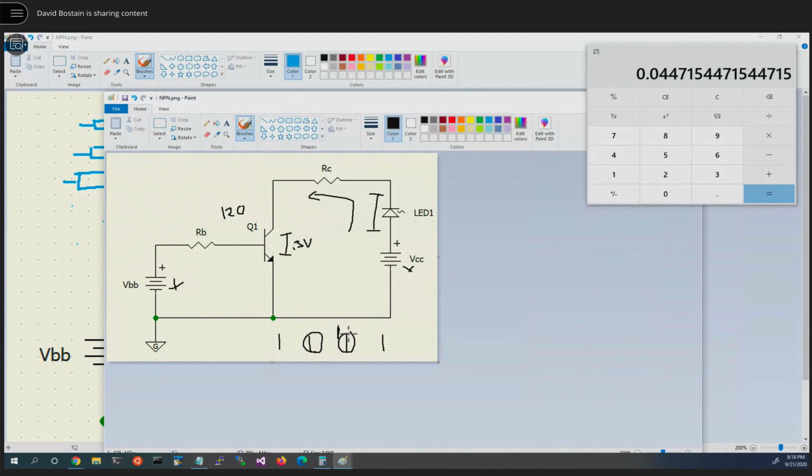Because once you work the problem and put in all the tolerances, this might exceed a range where it's not bright enough to be seen. Whereas if you came down here, it may get close to its maximum value, but it might still have a range that's reasonable. Can I create cases where neither will work? No, I'm going to create a case where the value you would have would work, which means it'll fall in both of their ranges. But picking the right one can become kind of artsy, crafty, depending on other things I might do in the circuit. So for now, if it's between two, you can probably pick either, but probably the better choice is pick the one you're closer to.